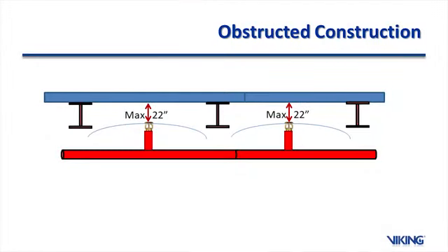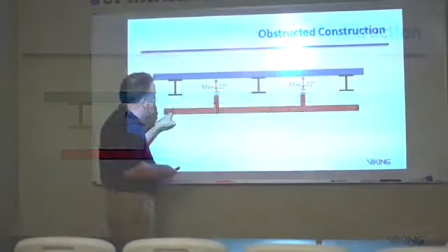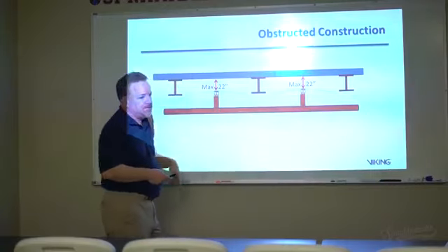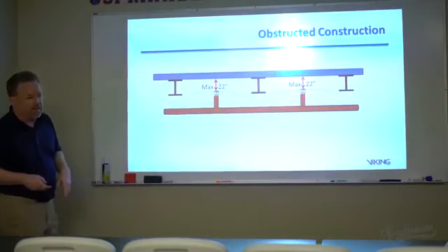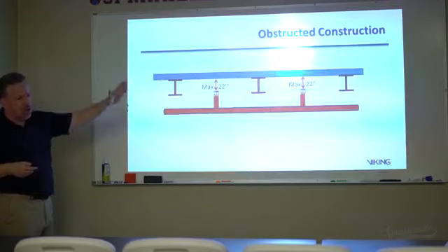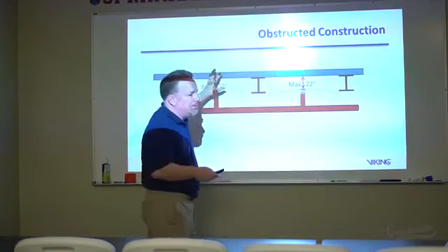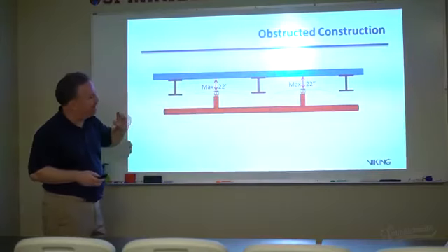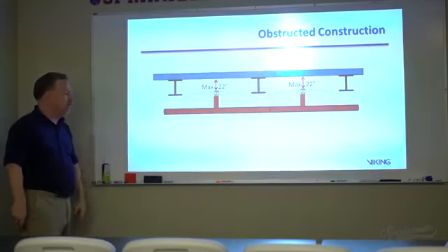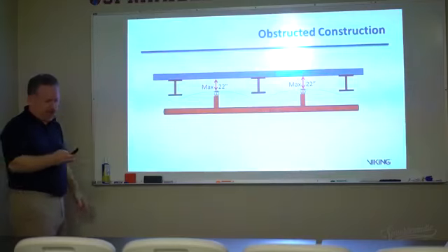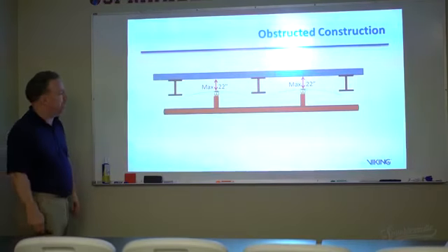Now you've got 22 inches going all the way up, and you're still below that line. But again, it's slow, so you don't have to worry about these being an obstruction to your spray pattern, but you do have to worry about the fact that that whole pocket slows the operation of your sprinkler down.